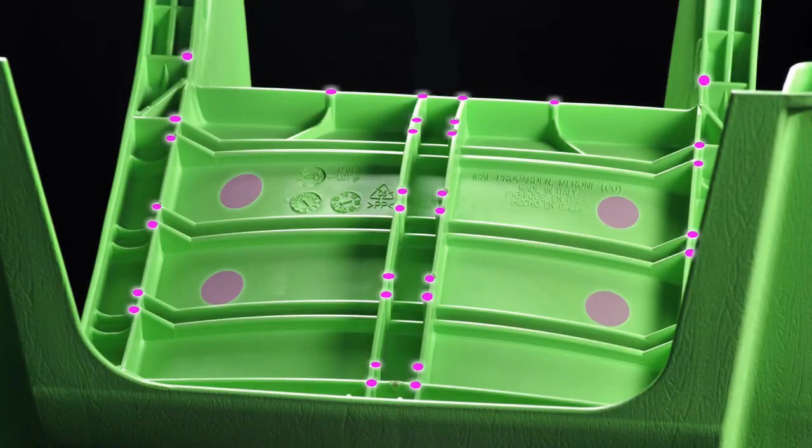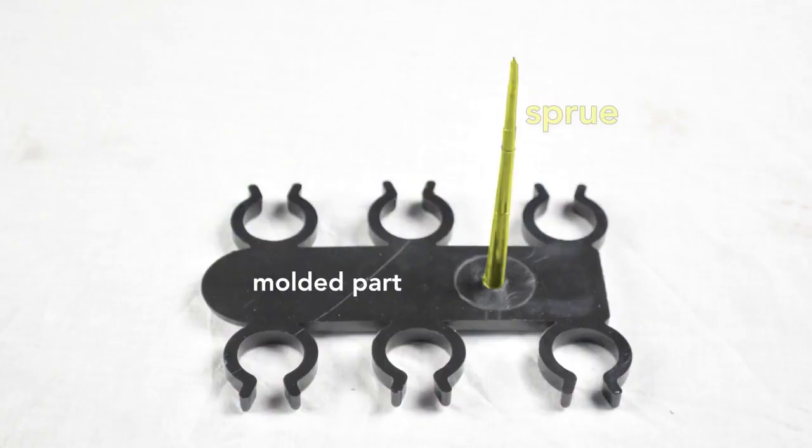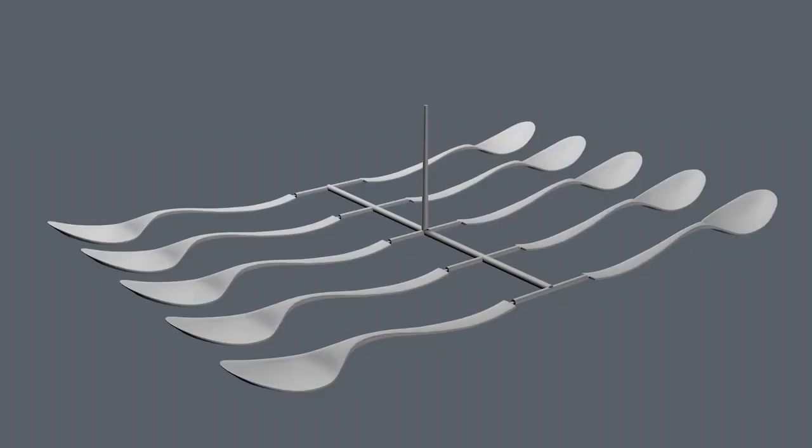When the part drops from the mold, an operator has to remove the sprue, that section of plastic that connected the injection unit to the mold. Sprues are manually twisted or cut off the part. Sprues are attached to objects only in molds that make a single part at a time, like a chair. Smaller objects are made in multiples in a single mold. In these, the sprue connects not to the part itself, but to a network of distribution tunnels called runners.